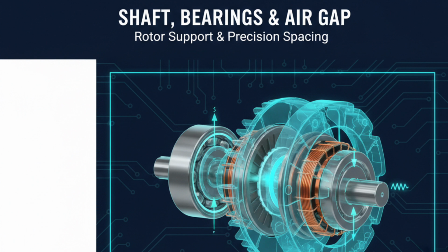Between the rotor and stator exists a small and carefully controlled air gap which strongly affects magnetic flux, voltage regulation, and vibration behavior. An uneven air gap can lead to noise, heating, rotor rub, and even serious mechanical damage.